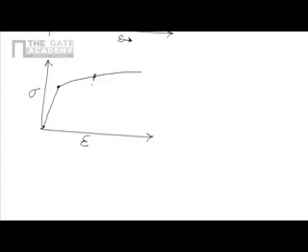It will drop down from there like this. This line is equal in slope to the elastic line. This portion is the permanent deformation in the material. This is called plastic set.